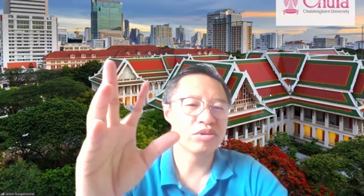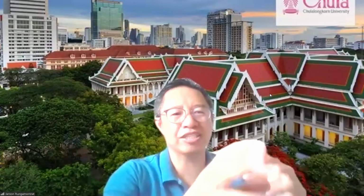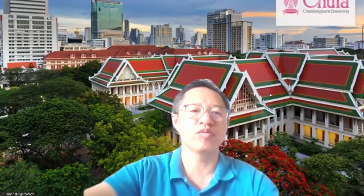That is the common sense you can get from the picture that I gave you. When you try to verify the solution, you come up with something consistent with your common sense. For example, if I have a body that can experience rigid translation in the x1 direction, then when you solve the problem and verify all the conditions, there will be one constant left in u1. The constant left in u1 will represent the rigid translation in the x1 direction. So they have to be consistent in that way.